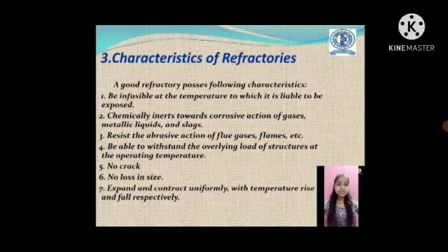My third point is characteristics of refractories. A good refractory possesses the following characters. First, be infusible at the temperature to which it is liable to be exposed. Second, chemically inert towards corrosive action of gases, metallic liquid, glass, and sludge.